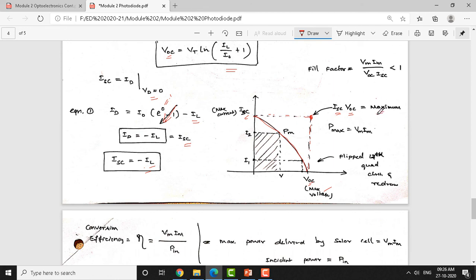This is nothing but a power, the maximum power you can extract from this. Now, where do you operate the solar cell to obtain the maximum? You cannot operate at this voltage here, because that is very difficult. If you observe the characteristics and choose a point here, and observe the region under the curve, if I shade this region in a different color, you can see this is very small. So, the V into I, whatever you choose here, this is V, and if I choose this as I1 here, that area and coverage is going to be very less.